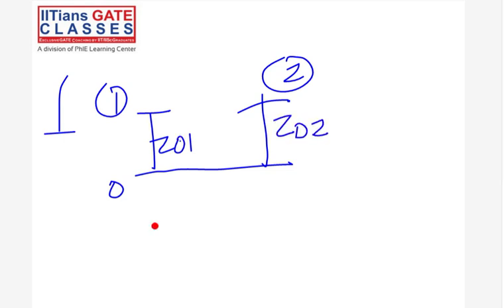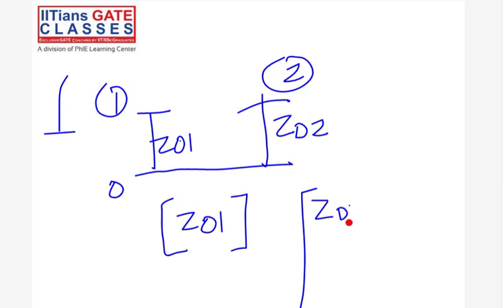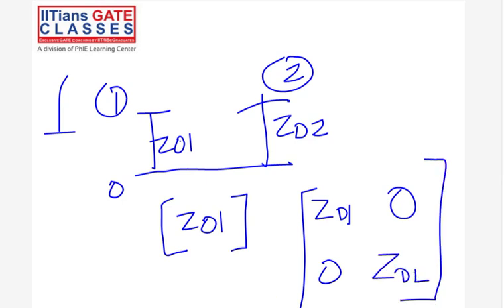So the set bus would be, you're basically adding set 0 1. Step 1 is adding set 0 1. Then actually the node to which the second element is connected is not 1. So instead of copying it here, you'll be copying the impedance of the node that is referenced. Make sense? Makes sense, right?